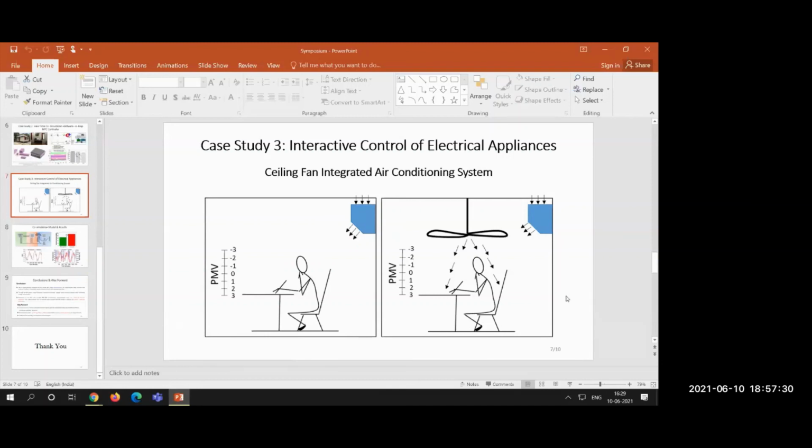Yes. Okay, so if we have ceiling fan combined with the AC, then the thermal comfort will be more. Yes, that's what this study says, because thermal comfort is not just temperature, like we are just operating the air conditioner in the room, but our thermal need depends on 7 kinds of variables that include the air velocity, the clothing that we wear, our outside environment, our indoor environment, our physical activity, metabolism, everything is contributing to our thermal comfort.